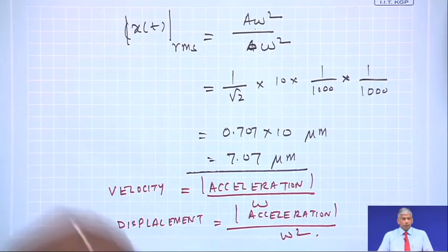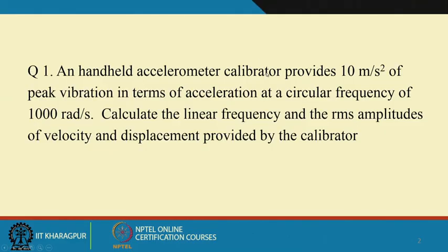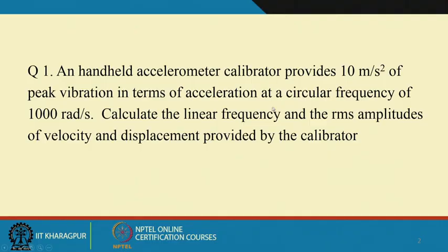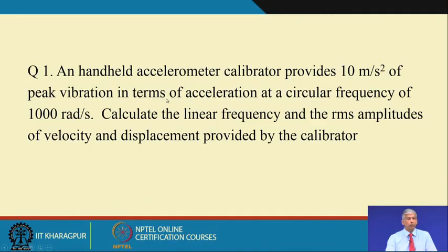So, this becomes a very handy tool in the field once we have this handheld calibrator. So, whenever I get some x voltages, I can know what this x voltage actually corresponds to. Sometimes in the field, the manufacturer sensitivity would have changed, and this kind of calibrator helps you do the field calibration.